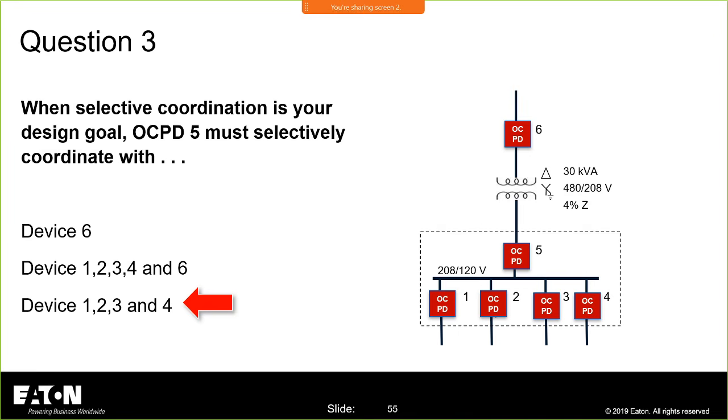All right, I'm seeing some dialogue on YouTube. The question was, is the fuse going to operate in the current limiting region down at the 1000 amp fault level? And Dan Neeser noted that the fuse becomes current limiting where the clearing time of the fuse is faster than 0.01 seconds. So when the fault current is increased to a point where my fuse curve crosses 0.01 seconds, I'm entering the current limiting region.